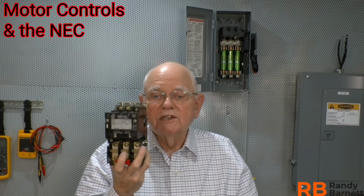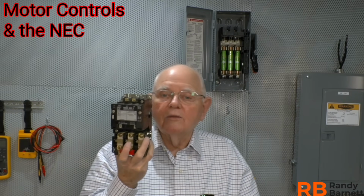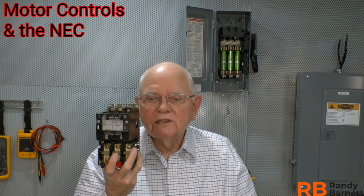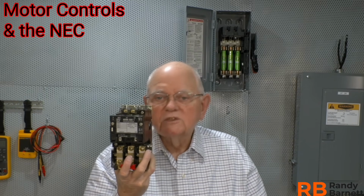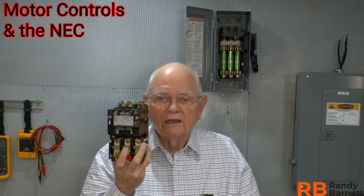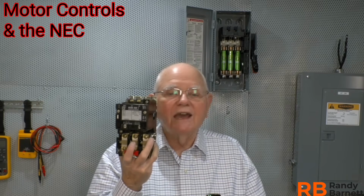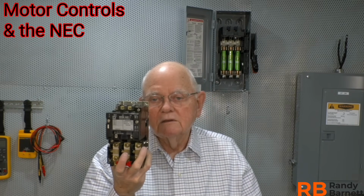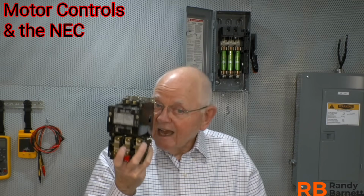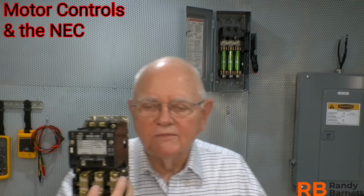The other issue, and one of the big issues, is that I have overridden every control element within this circuit when I do that. Any safety interlocks that I have, if the motor was not ready to start, not ready to turn, if I had a light curtain that had triggered a shutdown of the motor or whatever, it doesn't matter. That motor's going to start, and somebody could get in trouble on the other end. So, we don't go out and bump motor starters, okay? Not a good, safe thing to do.